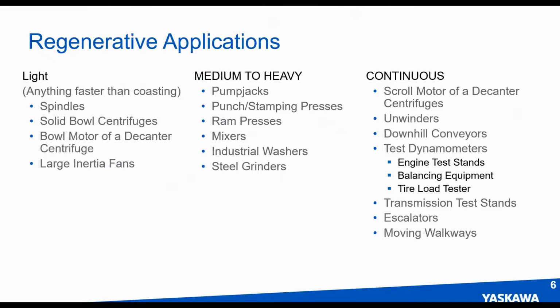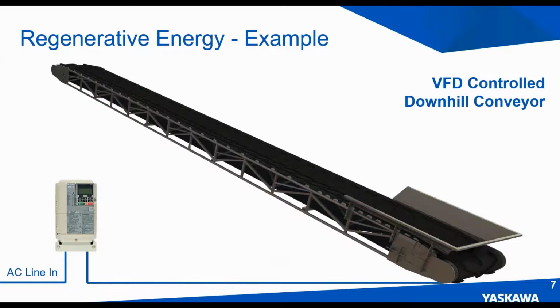The first is light duty, which is basically all forced deceleration applications. Again, forced deceleration is whenever regen occurs due to you trying to stop the load quicker than it would normally coast to a stop. Medium and heavy-duty applications are the oscillating unbalanced loads, pump jacks, rams, mixers, and continuous regen loads are loads that continuously regen. No brainer there. We'll bring this list up later in our presentation, and it'll come in handy when we're sizing some of our drives.